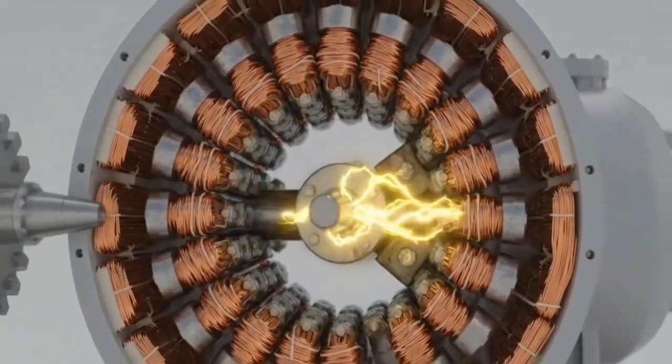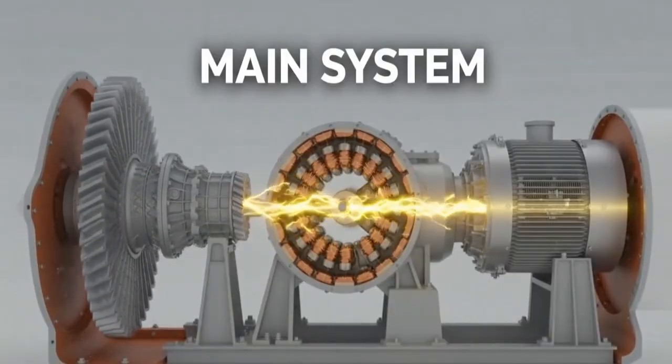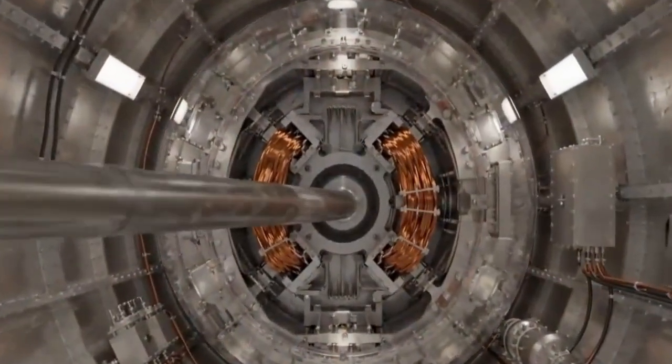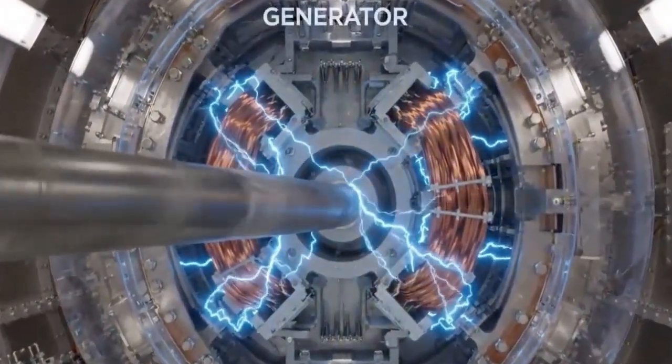The gearbox carries very large loads because it constantly transfers torque from the blades into the generator. Bearings and supports keep the shafts aligned, reduce friction, and help the drivetrain run reliably. The gearbox also needs lubrication and cooling, because friction between the gears can generate a lot of heat.